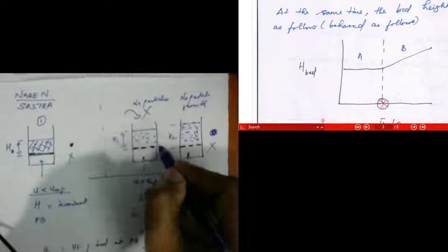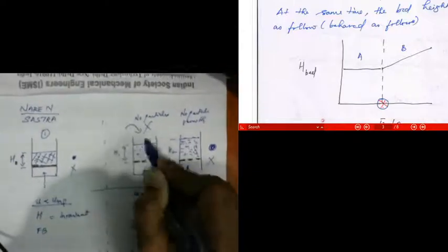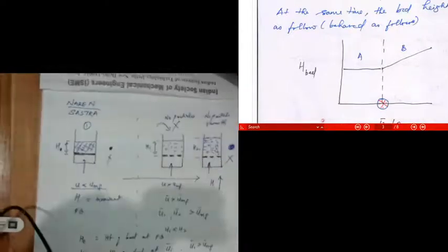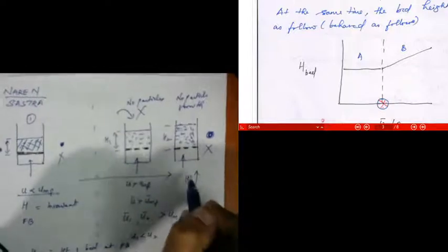So the distance between the particles increases, eventually, for the same cross-sectional area of the bed, the height increases, right? So that means as you increase the velocity here, you are putting in more kinetic energy. All this energy is now used to lift these particles up, to move this bed higher and higher, to increase the interstitial spaces eventually. So these particles are not falling down.